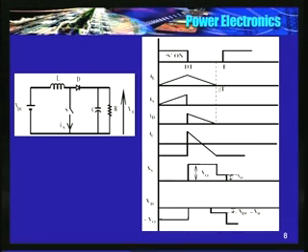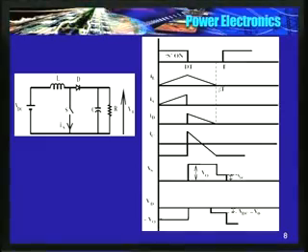They're simple. I'll just draw for the boost converter, and the remaining converters I will not draw. You may have to draw yourselves. Okay. So current becomes 0 at beta much before I close the switch for the second time. So when I close the switch for the second time, current starts from 0 and comes down to 0. This is the inductor current.